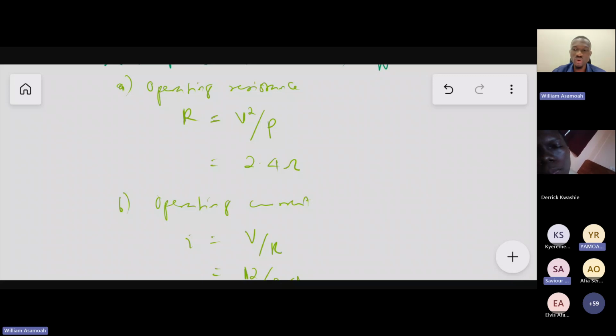And that is why we always say that if light goes off at your houses, turn off all the loads that were on. Because if you don't, all of them will turn on at the same time and these inrush currents come in. This is just a lamp and it's just 40 amperes.